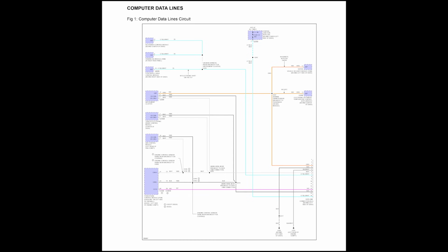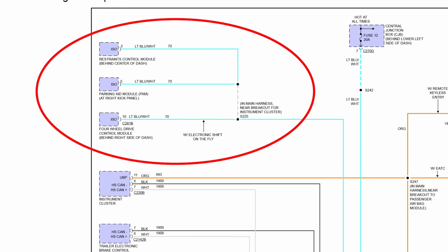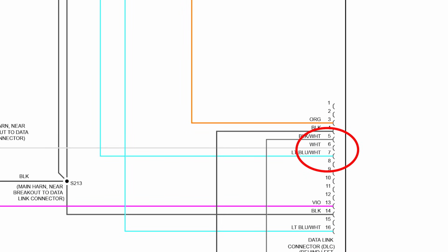And while the code definition doesn't specify what that third module may be, I think we all have a pretty good idea of which one it is. But to be sure, let's pull up the communication bus network diagram to see exactly who's on what network. There are three networks on the Ford. The first network is a single wire ISO 9141 bus that, unlike CAN and other networks, does not support intermodule communications, and it connects to the DLC at pin number 7.